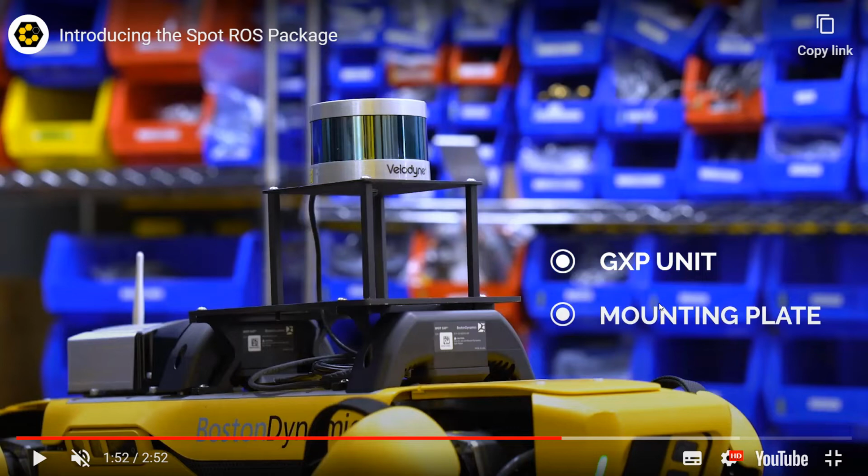You have seen the evolution of the robot dog. It's actually like 15 years of work. So that is the core part of this robot, and they will not disclose that. The source code is proprietary, and what we are working on is the top layer. We will not get access to the controller code, but we can give the robot commands. If you send a linear velocity, it will move forward. If you give an angular velocity, it will rotate. And also we can set the joint values. That is the ROS layer.